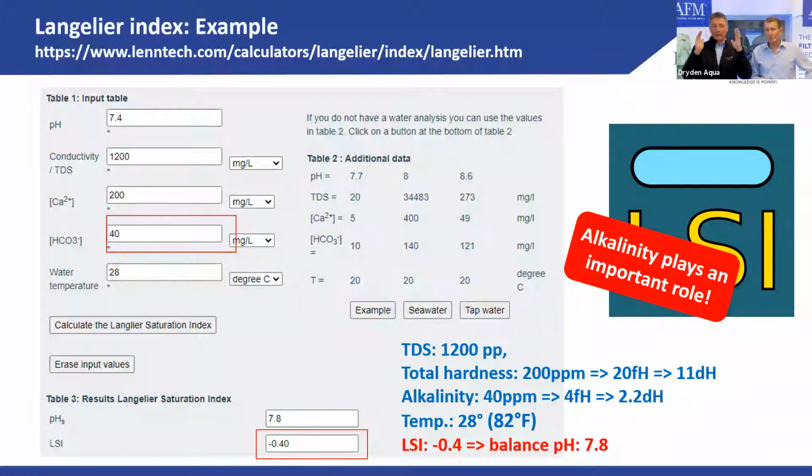And alkalinity is consumed. It's consumed if you add an acid. It's consumed just by evaporation, when the CO2 is gassing out. If you heat up the water or move the water, you lose CO2, then you drop the alkalinity. If you dose APF or any other flocculant, it is always acidic. So this is something that you have to bring back into the water.